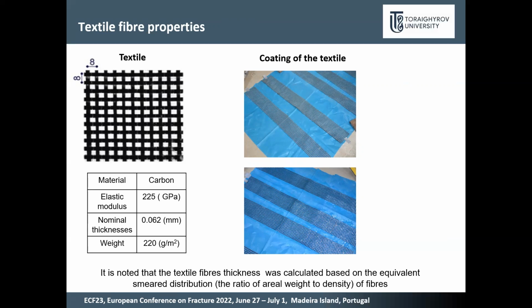Additional to that, all textile was coated with epoxy resin with the following procedure. The textile was cut in strips with width 120 millimeters and length 1000 millimeters.